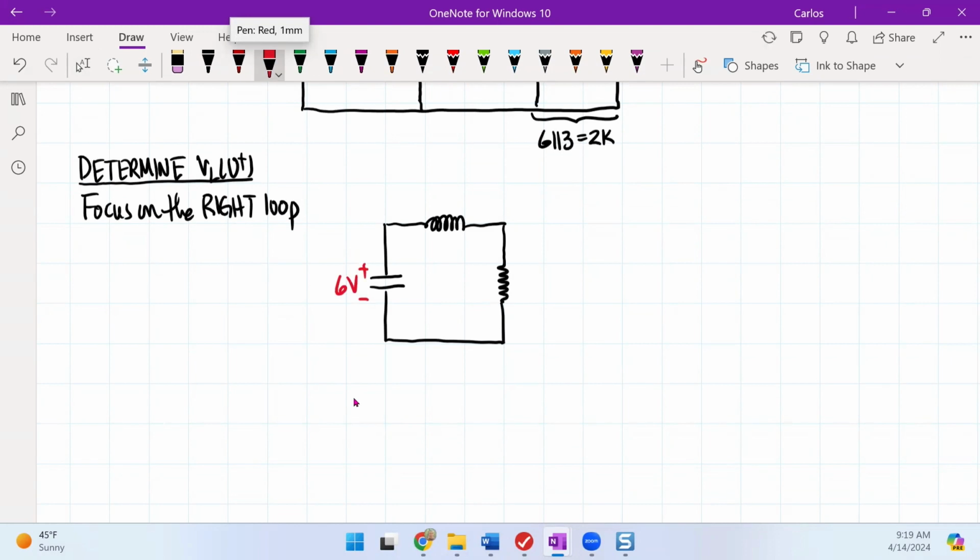It cannot change. So our focus is to calculate the inductor voltage at 0 plus. That immediately tells us that we have to use KVL, but the condition is that IL of 0 plus has to remain for an instant at 1 milliamp.